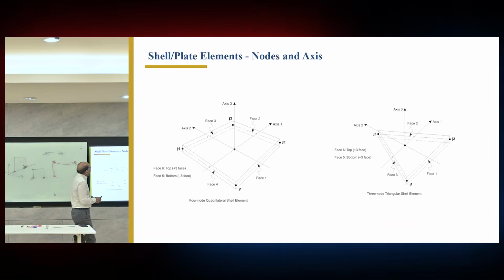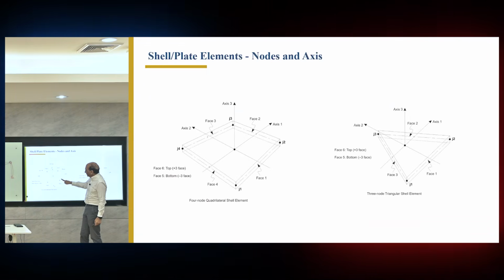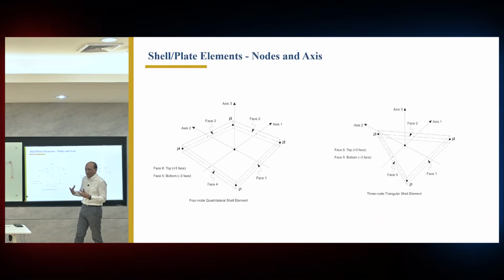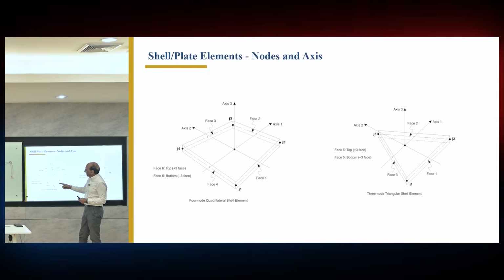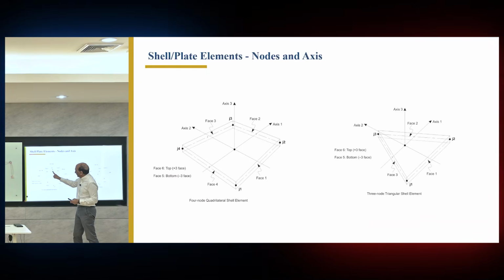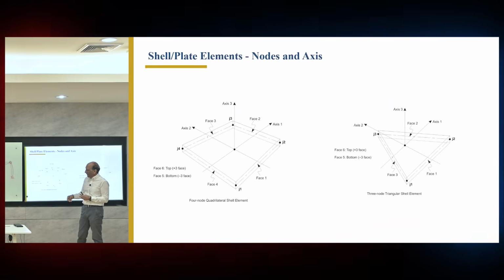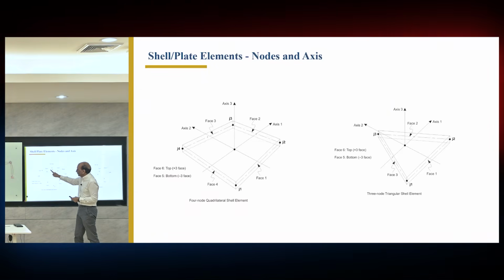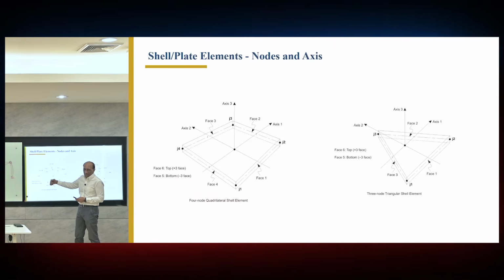Okay, this one here. First of all, the shell element has 4 nodes. Typically, the standard shell, plate, or membrane element has 4 nodes. So this is the most confusing part between ETABS and other programs. ETABS numbers them J1, J2, J3, J4, like this, so they are going in this direction.